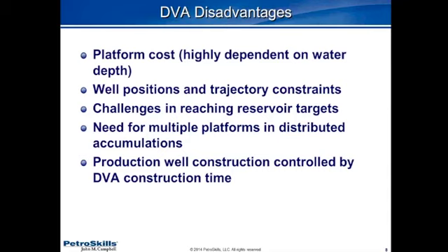The big driver for the cost can often be the locations of the subsea reservoir targets, which can be a long distance away, and as we mentioned earlier, if they are at a radius larger than about 4 to 7 miles, not feasible, thus requiring multiple platforms perhaps.